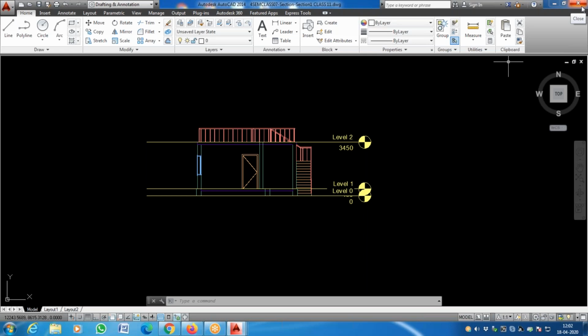Now, if you feel, oh my God, I'll do all these things in AutoCAD, then you can go to individual floor plans and export into AutoCAD, elevation into AutoCAD, section into AutoCAD, compile them in AutoCAD, and the layers won't clash. It will have perfect layering names because the layers are created by Revit itself automatically. So it won't clash. There won't be any two layers clashing. It will all merge together so well, and then you can print it from AutoCAD itself directly in the place where you're printing.